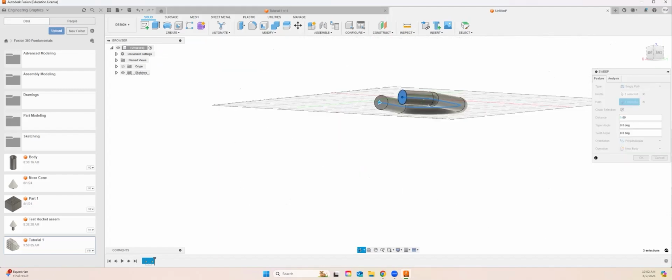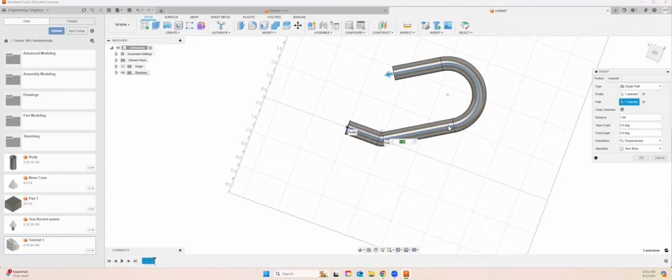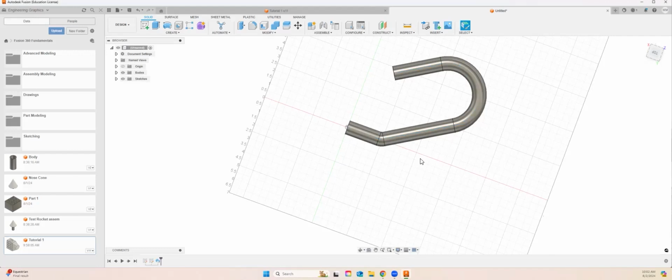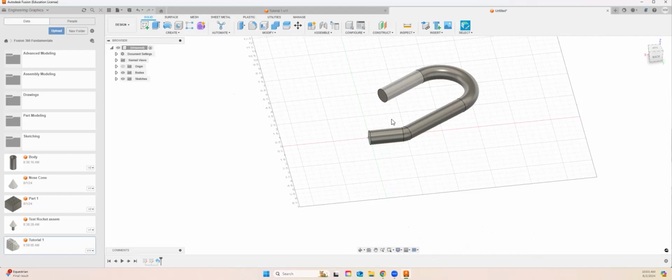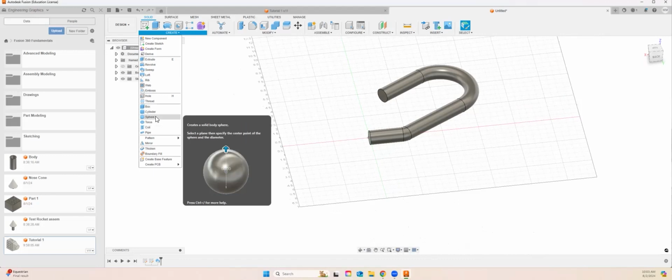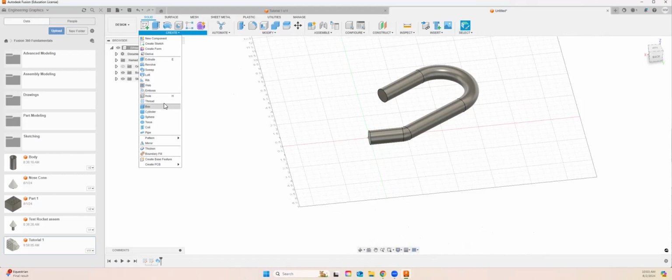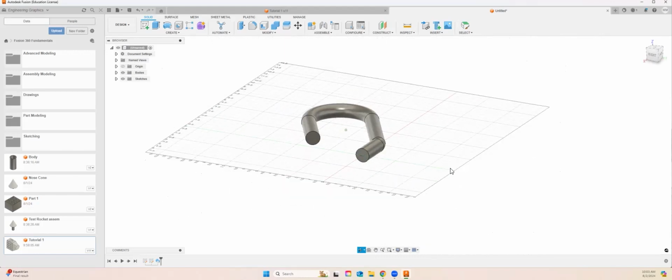So you can see, if you want to make a pipe or a specific shape, you can do that. Just make sure that the curves are smaller than the circle, so that it doesn't overlap. That's why we're gonna smooth some of the edges. Okay, and we could have done a little more, but this is our sweep, so you can create many shapes that you want. You can play around with the torus and so on. Coil, the pipe, you see already does that. So play around with some of those later. The sphere, revolve, and so. But for now, this is just how you do the sweep, and that's it for this one.